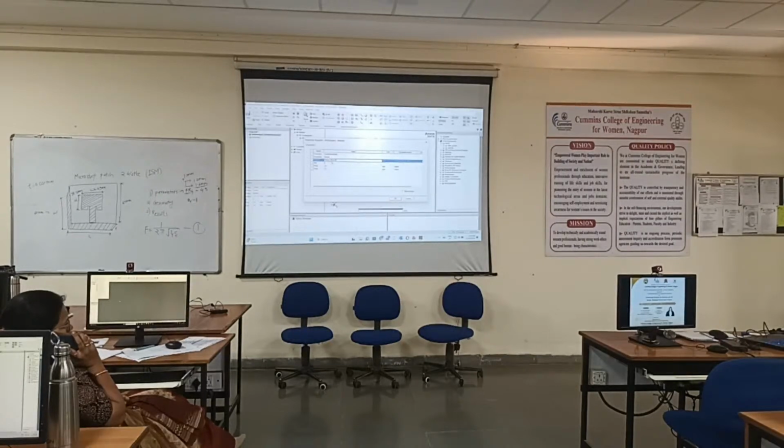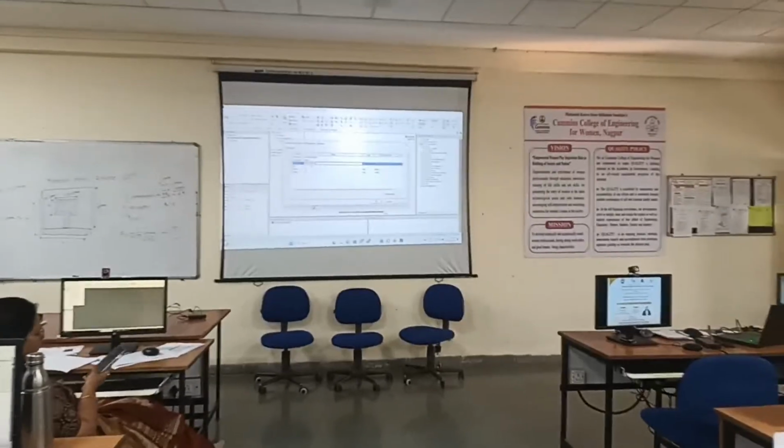Click on below this rectangle one, create rectangle is one of the options. Double click on create rectangle and in that first remove the position values, whatever is available in front of your pop-up window, and type there minus 30, comma minus 50, comma.